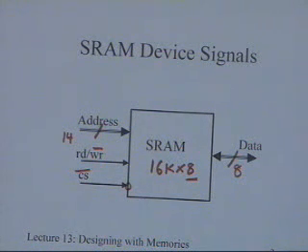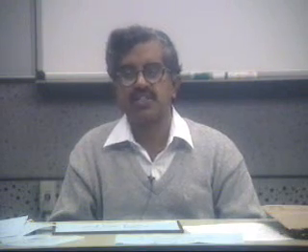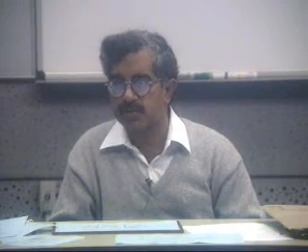And today the device cost is, if you're mass producing a device, you take out the technology and the design cost in the initial few months of the product being in the market. Then basically the cost revolves around the cost of fabrication, which is fairly small, and the cost of the package. And the cost of the package is directly dependent upon the number of pins you have. So if you really want to produce a low cost device, you have to reduce the number of pins.